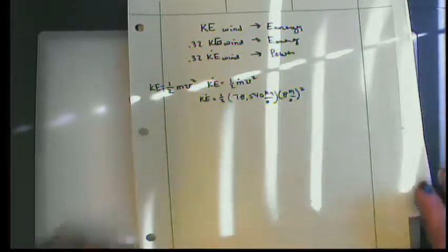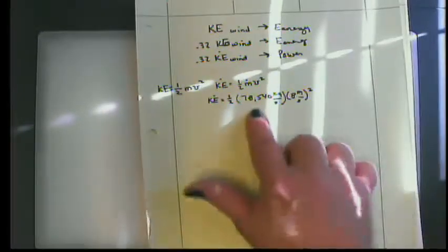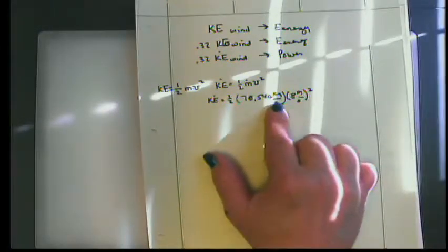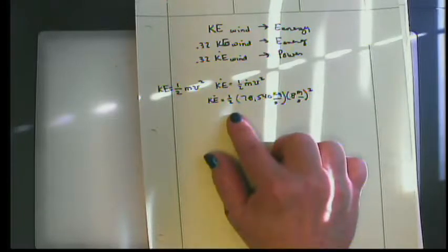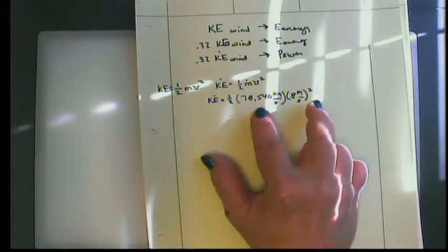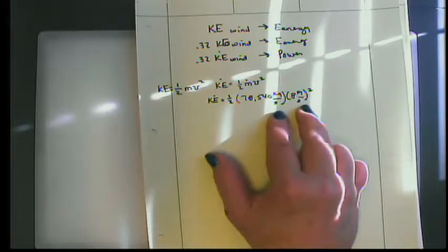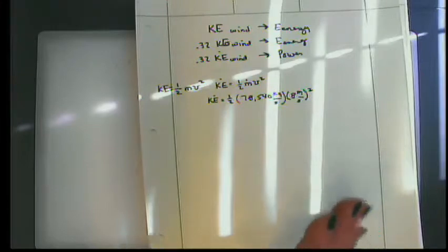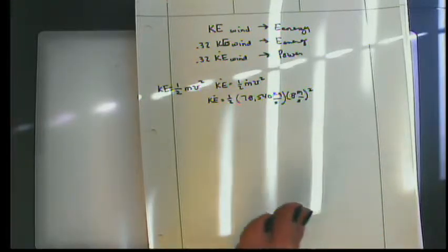The upshot of this is when you have a wind turbine, and other kinds of turbines as well, velocity is king. In other words, rate of kinetic energy available to you is based on the cube of the velocity of the wind. So the velocity of the wind is the utmost dominating factor in how much power you can get out of a wind turbine.